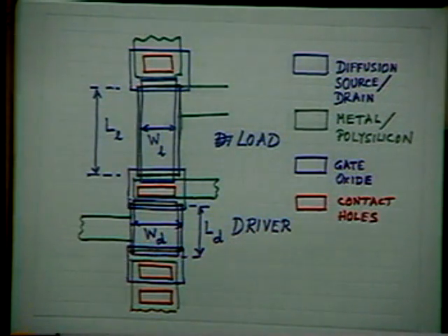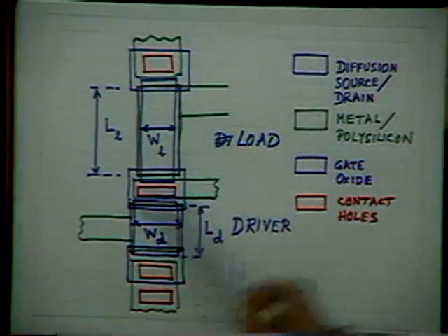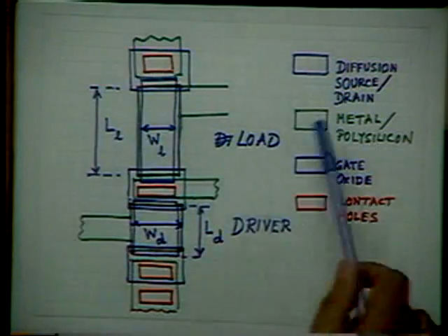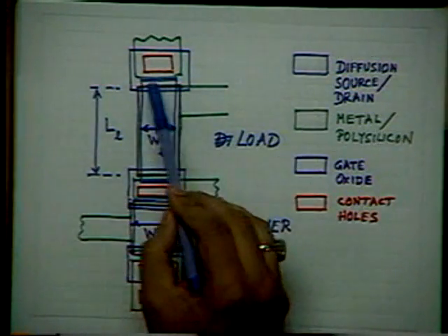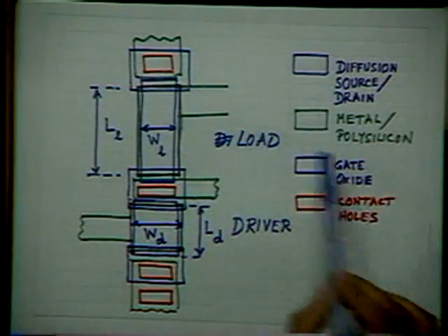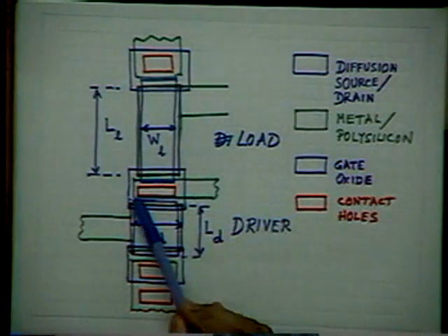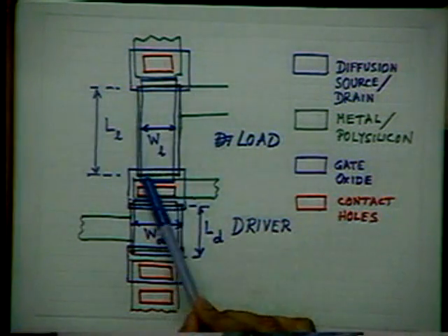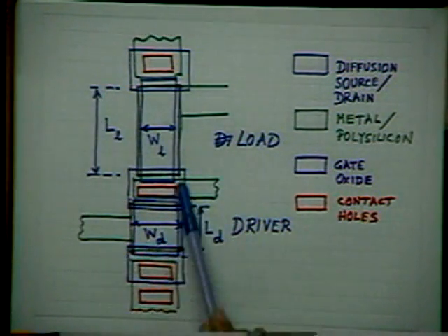All right. The entire substrate surface is covered by a very thick oxide called field oxide. I told you in the last class. Otherwise the surface is covered by a very thick oxide, which I have not shown here. But only this region, shown by this violet colored rectangle here and here, the oxide is etched off, and a very thin high quality oxide called gate oxide is created. So this region and this region.